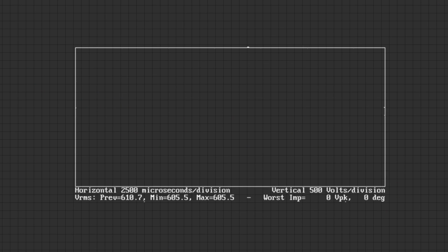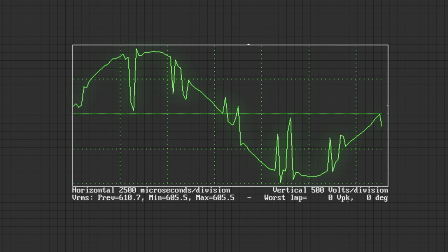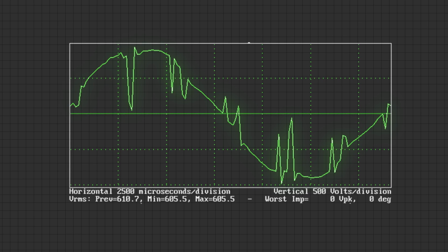Then when the current got severely distorted and the voltage got distorted even more on the generator bus, the generator's regulators actually couldn't synchronize the operation of the generator with a 480 volt bus, and the generator actually slipped a pole and created the evil noise.